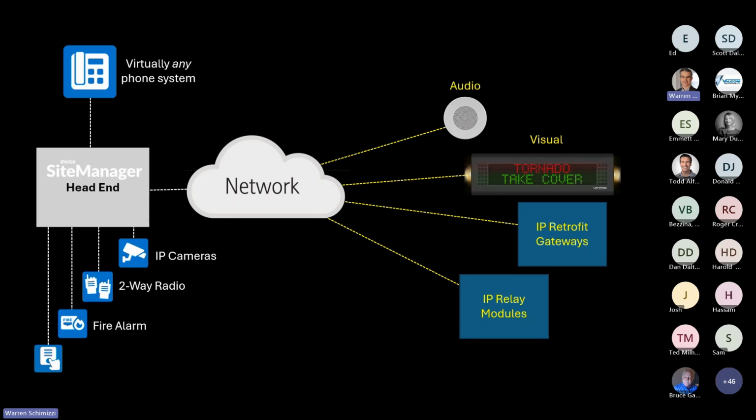The other thing, and I want to make sure that you understand that this is not an automatic thing. This takes an awful lot of pulling strings in order to make it happen, but we can override the fire alarm if the AHJ and the fire marshal agree and the customer wants to do that. The reason is, you think about all of the active shooter events that have happened in the past, most of them, the way that they got people out into harm's way was pull the fire alarm. So the people that are on premise have a very good idea of whether the fire alarm is real or not and can override it. So again, you have to go through a lot of hoops to make that happen. But technologically on our end, it is possible. It's just a matter of whether you really want to do that or not.